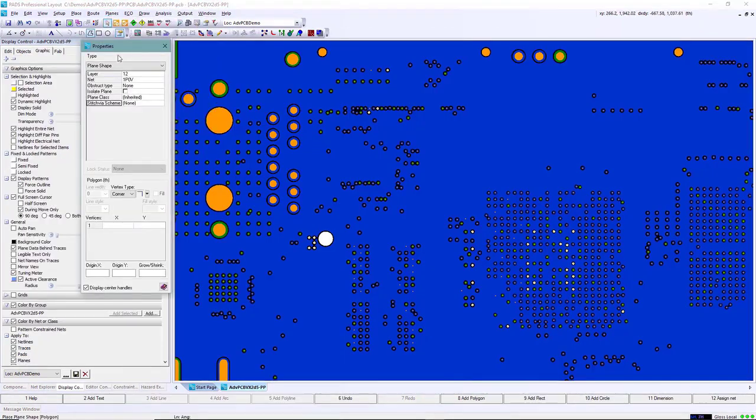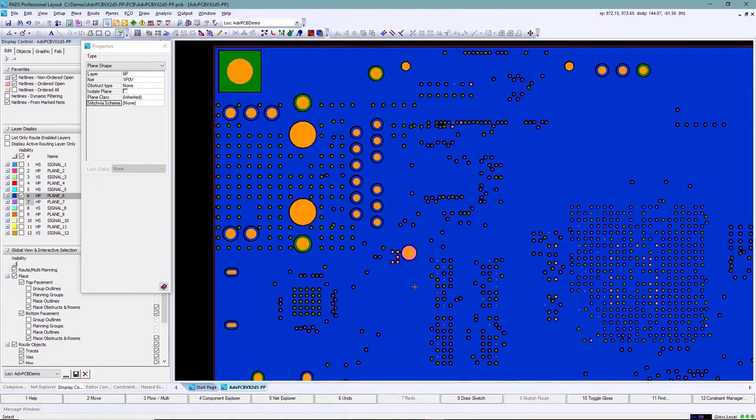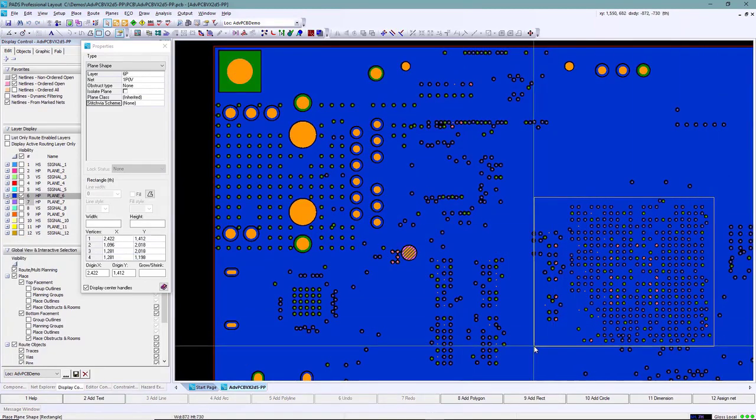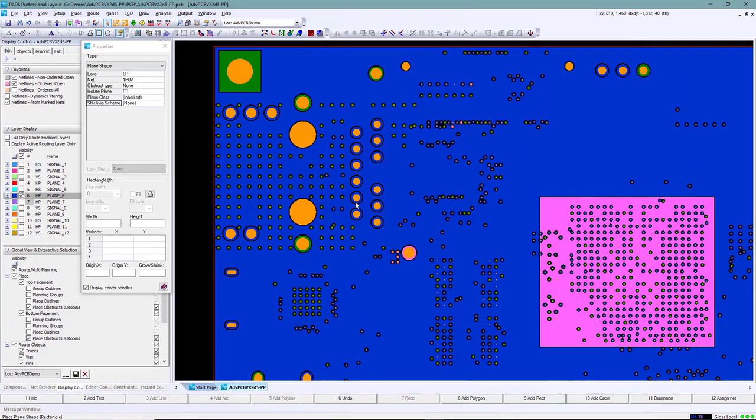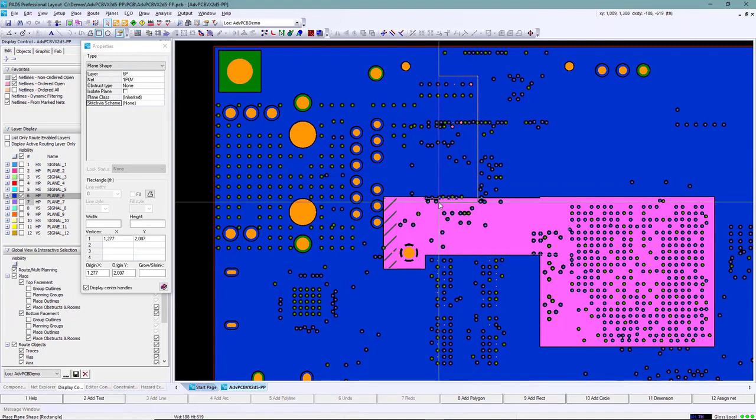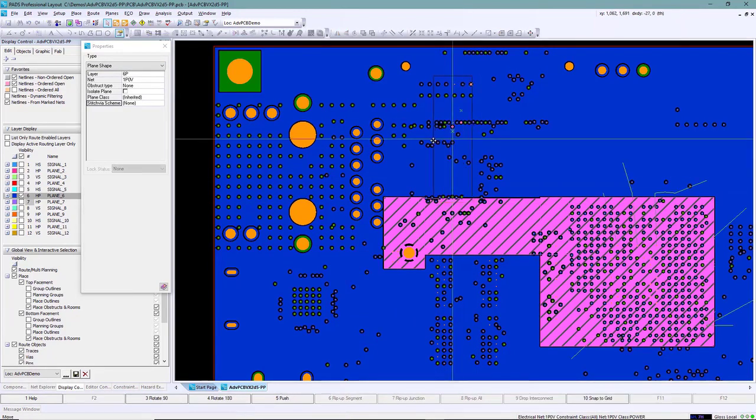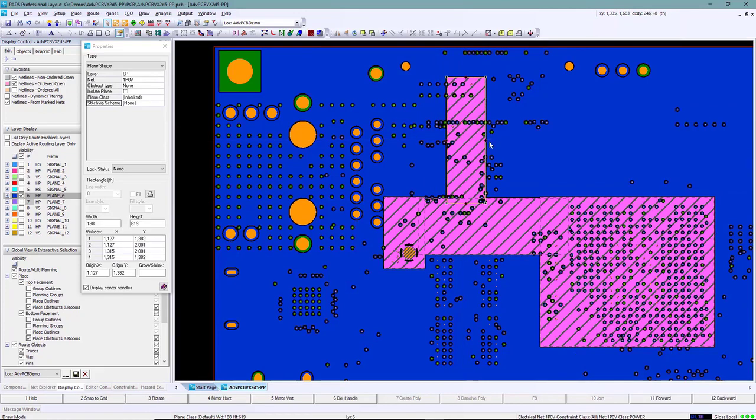Working with a 4 or 40 layer board, at some point we need to create embedded planes. As I showed earlier, using simple rectangles and circles instead of drawing complex polygons dramatically reduces the time it takes to create embedded planes. Let's go through two examples. First, we will create an embedded plane using rectangles and merging of shapes. What's the advantage of taking the time to merge shapes? It allows us to easily move the shape at any point and change properties.